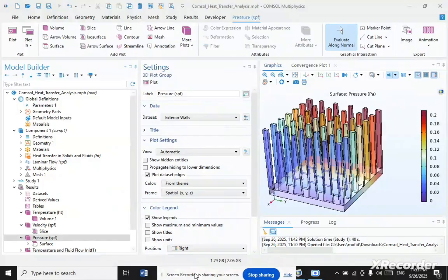It was observed that vortex formation downstream of the pin fin significantly influences thermohydraulic performance and can be analyzed with the help of a streamlined plot of fluid flow. Based on different studies, it was concluded that the optimal micropin heat sink for single-phase fluid flow should have a fin with sharp edge cross-section, pin porosity in the range of 0.5 to 0.6, tip clearance of 15 to 25% of channel height, staggered fashion, and stepped arrangement.